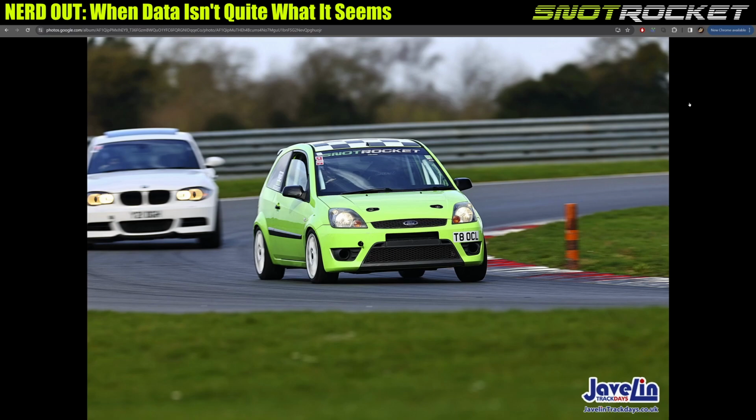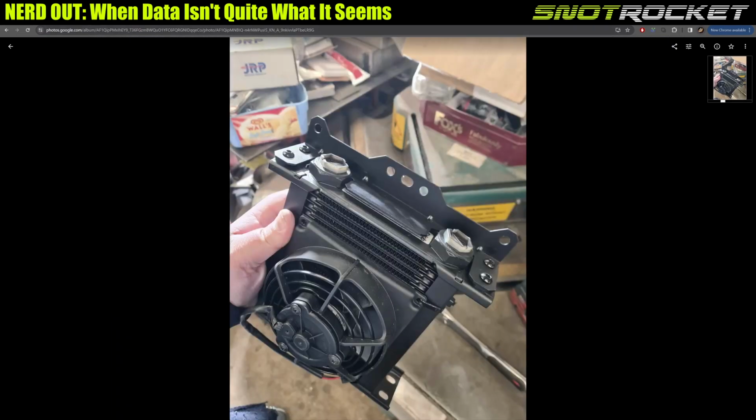So I looked at replacing that with some kind of passive oil cooler separate to that, and I'll go into how I've done that here. So I picked up a Setrab oil cooler here. It's 115 millimeters wide and it's 25 rows in depth. In theory, that would have a lower oil pressure drop across it rather than a big long cooler that goes all the way across the front of the car. And I decided to put a fan on here. This is a Spal fan that would ultimately be controlled by the ECU to help regulate the oil.